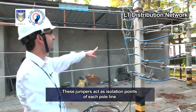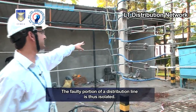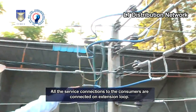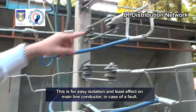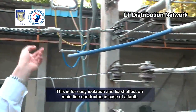These jumpers act as isolation points of each pole line. The faulty portion of a distribution line is thus isolated. All the service connections to the consumers are connected on extension loop. This is for easy isolation and least effect on main line conductor in case of a fault.